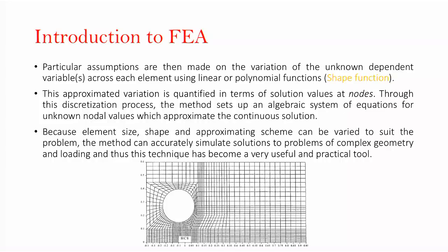So this is an example of dividing a thin plate with a hole into small elements. As you can notice here, at some sections of the plate, we use small elements or fine elements, and at some points, we just use bigger elements. When we use bigger elements, we basically increase the speed of solving the equations, or in other words, reduce the computational cost, right?